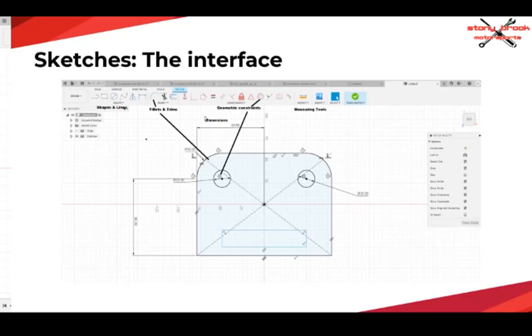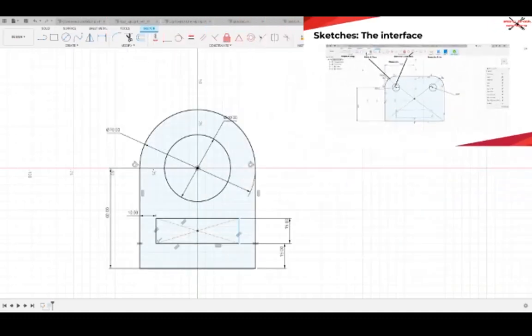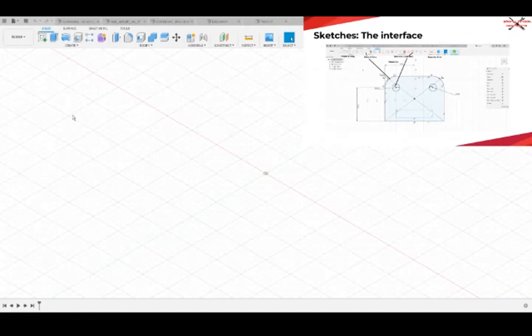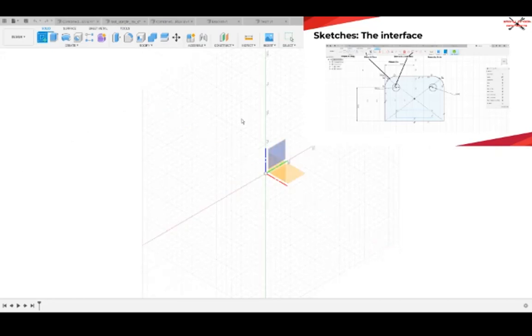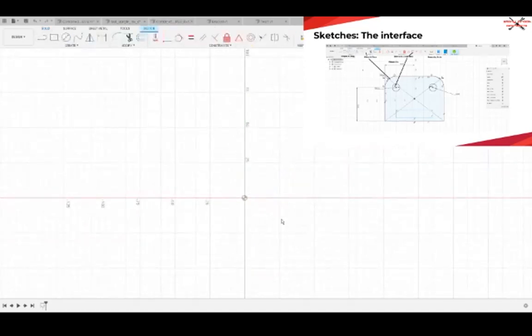Basically, when you have your interface in Fusion, there are a number of things that go into this large little sketch. So first off, when you make a sketch, you need to, and actually I forgot to implement this into the slide. So let's say we want to make a new sketch. So obviously we have to make a new design, all that jazz, and now you have yourself a little blank canvas. So first thing you obviously want to do is create the sketch and define what plane you want to use it on, because obviously CAD is a 3D thing, but sketches are defined in 2D planes. So once you select that, now you have this little canvas, which is akin to what we have in our example interface here.